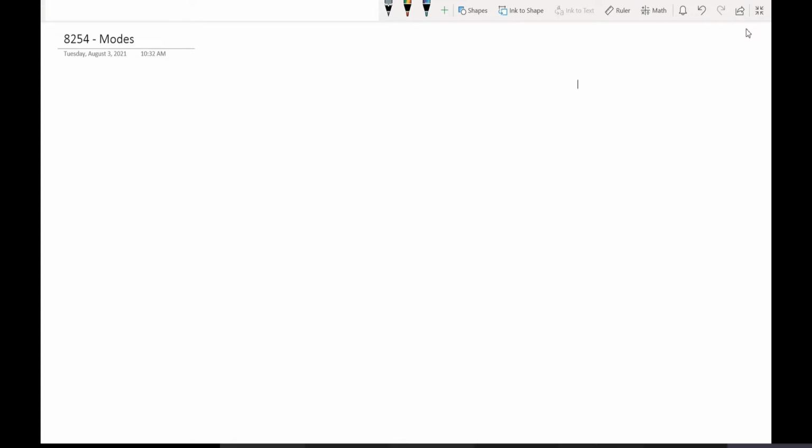So basically, there are six modes in 8254, and all of them have a unique waveform which will be coming out in the output. That output waveform is what we are looking to draw. As we have already seen, the output will be coming out from the counter, either counter 0, counter 1, or counter 2.